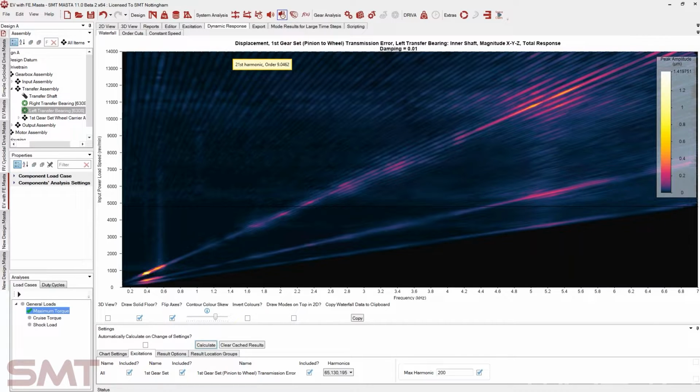So, for example, just to talk to you through a couple of these, I won't show anything on the screen particularly. So we have the inclusion of additional standards for micropitting and for scuffing. They've been included in Master 11. So the ISO technical standard 6336-22, part 22, 2018 for micropitting, and some others for scuffing. So they've now been incorporated into the software and can be used by all of our users in Master 11 or with necessary licenses.